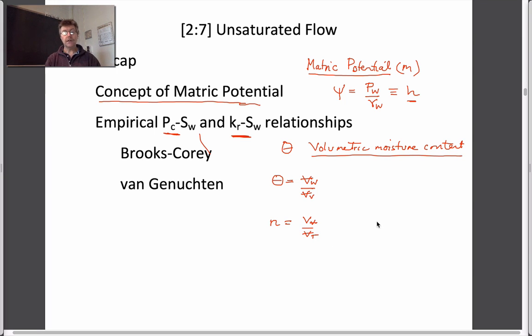And so, what's the other one we want to calculate? The volume of water is equal to what? The volume of water would be equal to, you've done this right, volume total times the porosity. This, by definition, is the volume of voids. I guess that comes from this. Yeah, that's just a rearrangement of this. And if you multiply this by the saturation of water, that would give you the total volume sum.